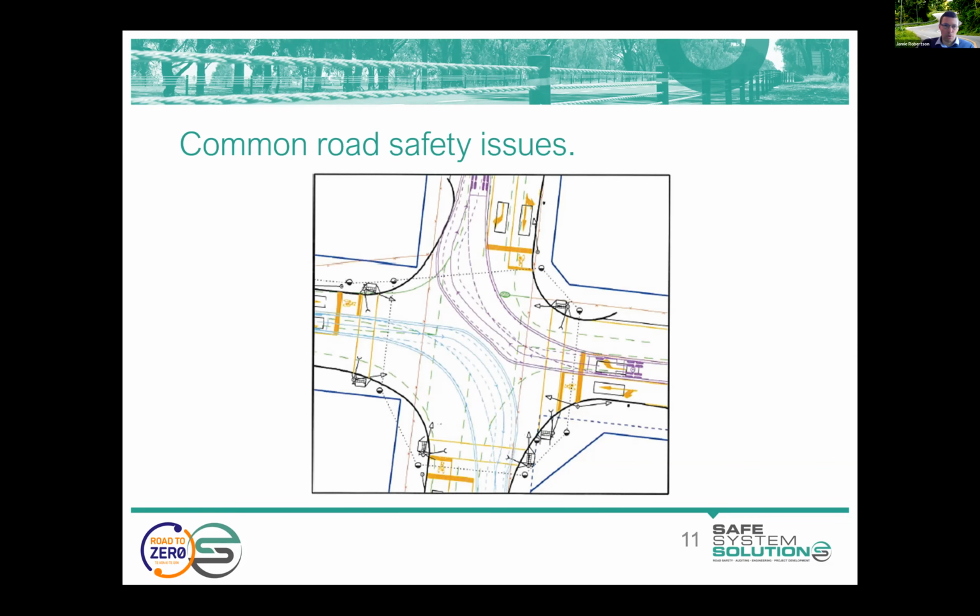It is desirable for a swept path for a turn such as this to be drawn on a single radius. This is obviously not. We have the truck approaching on a straight, undertaking a short turn, straightening out again, and then a tight short turn. So that's not how a driver unfamiliar with this location would be expected to navigate the intersection. If the swept path had been drawn in the desirable way, at the desirable radius with a single curve, there'd be quite an overlap between the two swept paths from either direction.